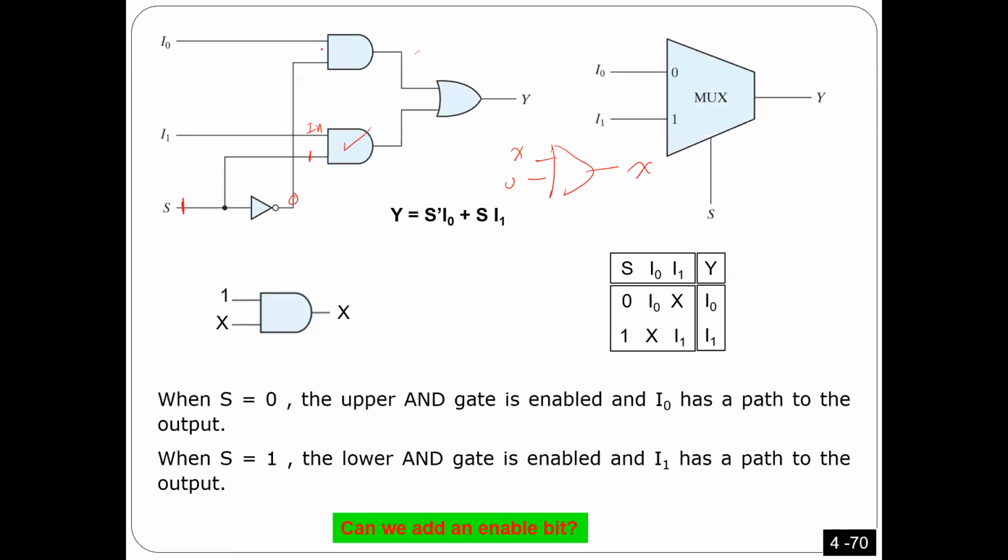And because the inverter here is 0, I'm going to turn this one off. As you will see, as explained before, maybe this is a very simple example, but when I go to a big example, it's the same idea. You will see for every case, we have one AND. If the selector is going to output this one, then this AND has to be on. That means all of its inputs are ones, and all the other ANDs should be zeros, as you will see now.